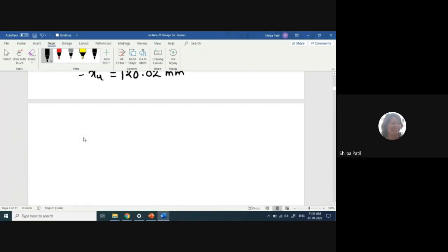Now, to be on the safer side, we need to do one more step here to make sure that whatever formula of MUR we are using is correct. That is based on the area of the steel. The formula we have to use, TU into ZU or CU into ZU, depends upon whether the given section is under reinforced or over reinforced. So we have to find out first whether the given section is under reinforced or over reinforced. For that, we have to compare XU with XU max, right? So what is XU max now for this beam? 0.48 into D. Tell me the value.